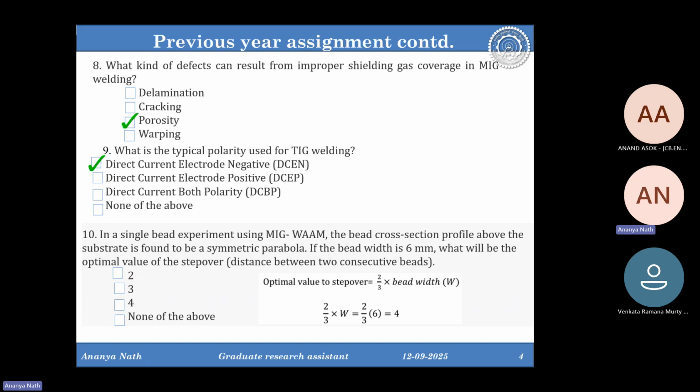What is the other one between the current? The options are substrate, sacrificial electrode. The question is, in microcasting, the arc is generated between the MIG welding gun and dash. Actually, it is between MIG and plasma. So it's the MIG welding gun. That means the metal is going to come from the MIG welding gun. That is the sacrificial electrode. So now we are making the circuit between the sacrificial electrode and the other one to make the circuit.